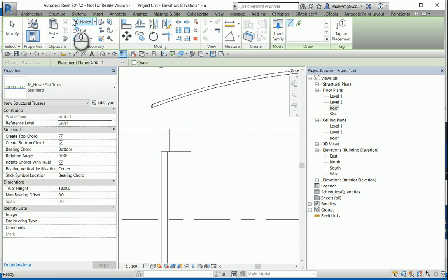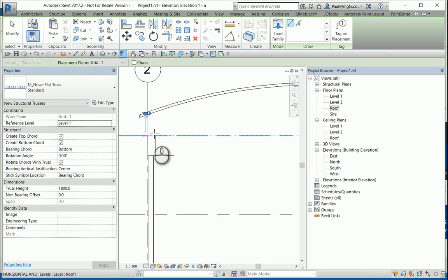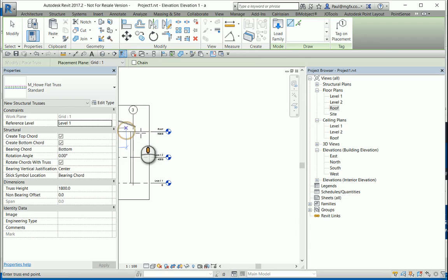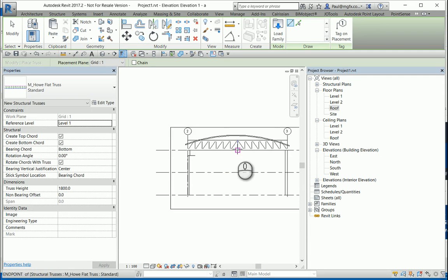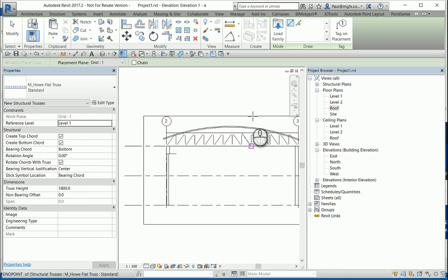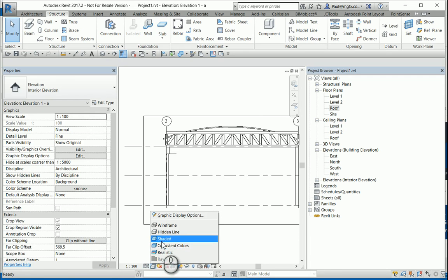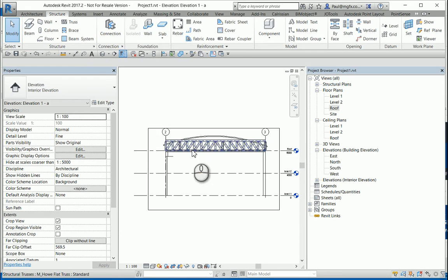Point number 1 now snaps to the intersection of those references, dragging that across. It is a little bit heavy on the memory. There we go, there's the intersection. It generates that truss. At the moment that truss is generated as if it is a railway bridge, basically, because of the switching out into fine detail view. There you can see it's using some really interesting sections, universal I-beam sections, to create that truss at the moment.